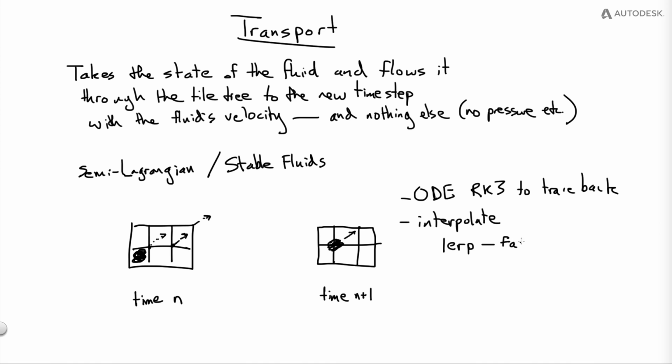This is an option. It's fast, but it tends to smooth things out, so we sometimes call that diffusive, which for some simulation scenarios is actually a nice effect. Things get smoother with time as they trend apart, and you see fog or steam dissipating into a smooth generic field. But if you want really detailed, pyroclastic looking smoke, this is maybe not the look you want.